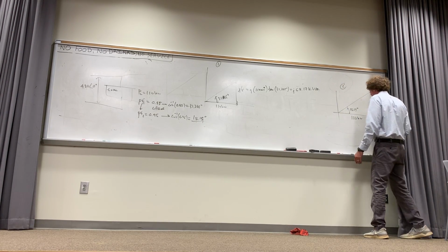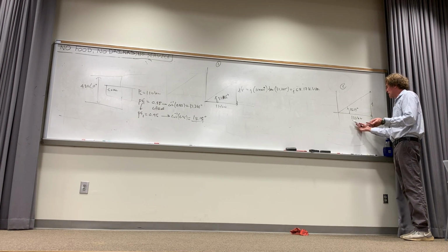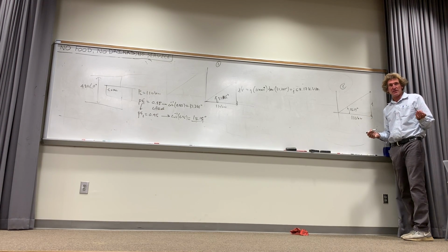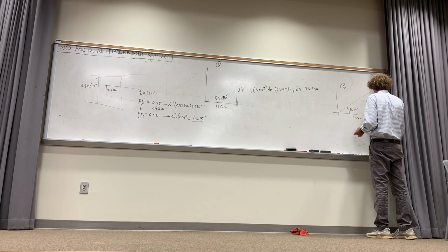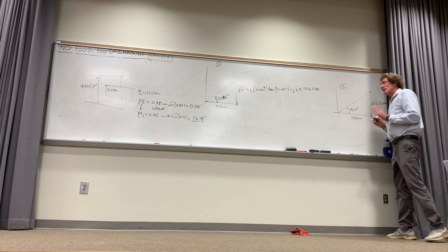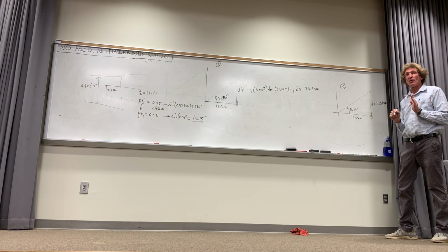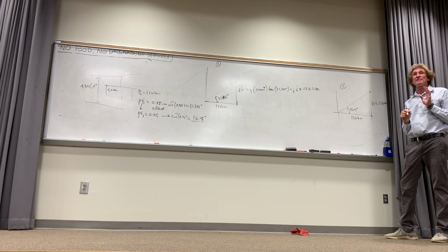Therefore, what is this JQ? Well, it would be tangent of 18.19 times 110. Can anybody give that to me, please? 36.15. So it's j36.15 kVAR. Everybody follow me? That's where I want to go. I was at 0.85, I want to go to 0.95, correct, class? Follow me on this?